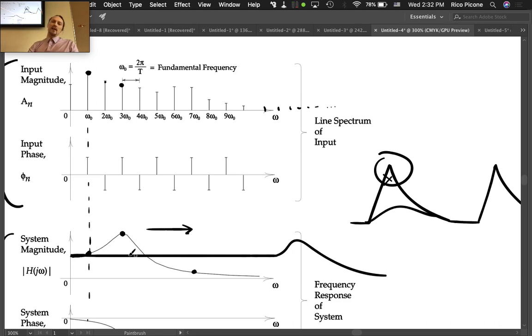So make it stiffer or reduce the mass, something like that. And then you have this input that would not get nearly as distorted, okay? So then your fidelity to the original signal might look more like this, and you'd be a lot better off. Your measurement would be a lot more accurate for the system that you're trying to measure, or the input signal you're trying to measure. So knowing when you might have this happen is really important.